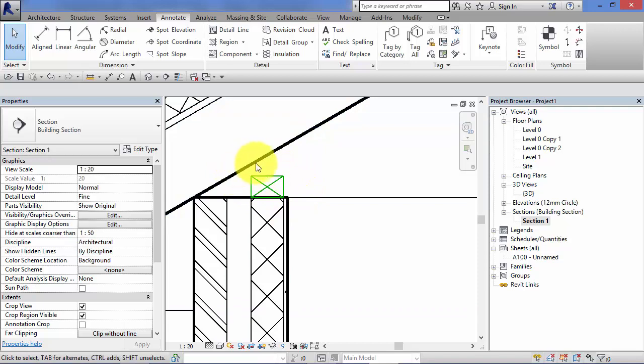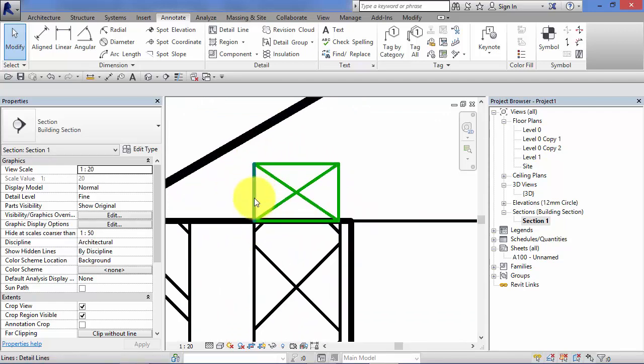We're not generally going to see them in many views. Typical section on eaves detail, that's where we want to see them. That's why we're producing it as a 2D detail. Now you could just draw it out with detail lines like that. What I would suggest is you're going to use detail components where we can predefine this 2D detail as a complete component or a 2D block, if you like, and just apply that. That's a more efficient way than actually drafting that component out manually with detail lines.